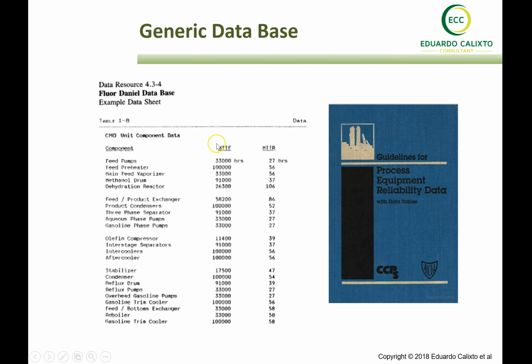What I'm trying to say is that we can use this MTTF as a mean and put some standard deviation. Then we have our increased failure rates in our model that can be anticipated by the preventive maintenance that we put in our model. That's the correct approach. We can use this database as a reference, but you need to be careful not to apply the PDF for random failures to all the equipment and run a simulation, because that will not represent the reality.